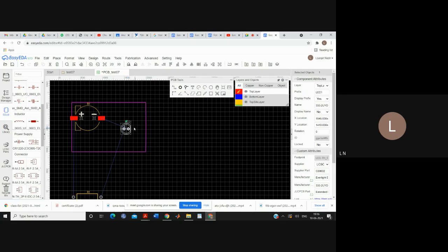So I will drag all these components. If I feel that they do not have a suitable placement, I need to rotate them, in order to avoid an overlap of the wire. Then I have a third component, a resistor. I am also dragging that. Let us keep all those components safely within the magenta border, within this rectangular box. I repeat, this rectangular box marks the size of the PCB that will be created.